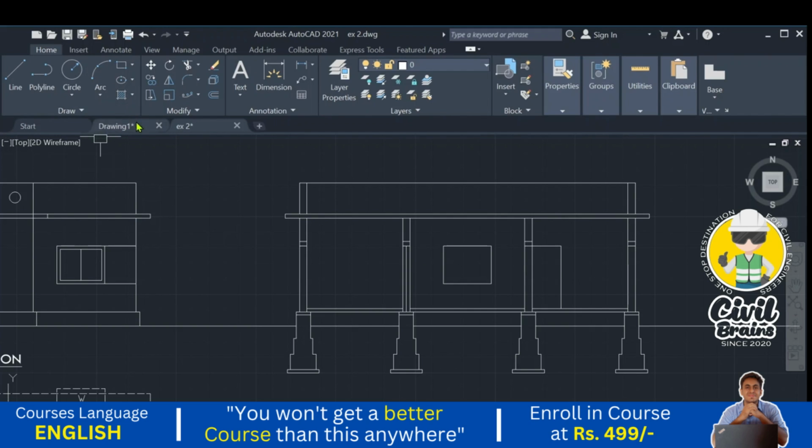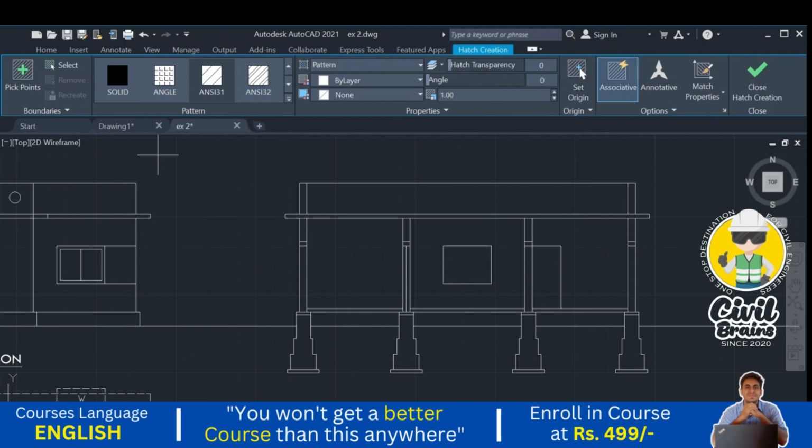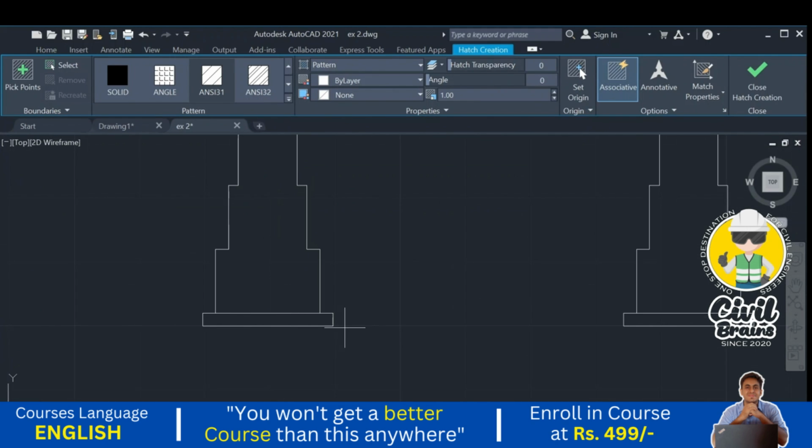So I go to the hatch command. The first hatch is PCC. PCC is made up of what? PCC is made up of concrete. So I go to the concrete hatch, I click here and put it on the PCC, but the concrete is not showing. I just increase the scale.